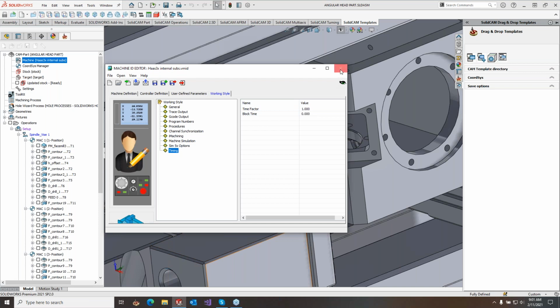This is also the same cycle time that gets used in the channel synchronization dialog when you do setup sheets, so the same time is shared everywhere throughout SolidCAM. This means drilling operations are probably pretty accurate. Machining toolpaths are generally not as accurate because there are lots of toolpath movements and deceleration, which is not perfectly accounted for in the cycle time. As we know, most machining toolpaths are off by 5 or 10%, depending upon the machine. Some are faster, some are slower.